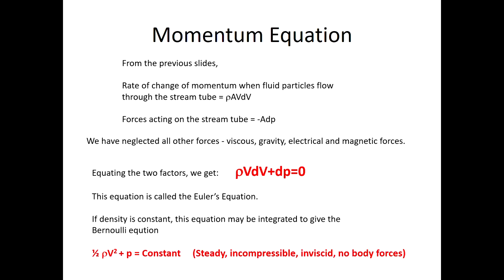So in incompressible flow, low speed flow, which is the first few weeks of our lecture, we will use Bernoulli equation. By the way, what is this constant called? Sometimes we use the word P naught, which is a stagnation pressure or total pressure. Hydraulics people will say stagnation head or total head because they are used to thinking of a column of water, head, type of a thing. But we will use a stagnation pressure, P naught.